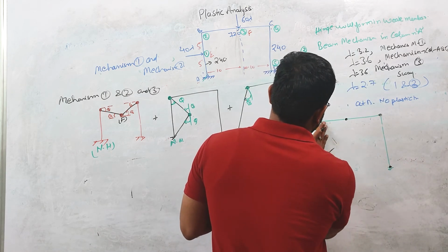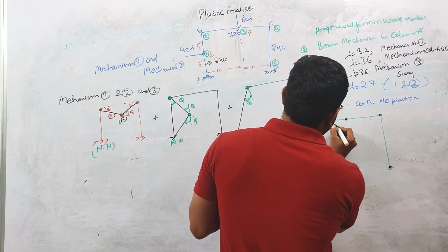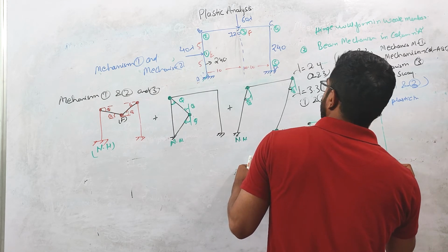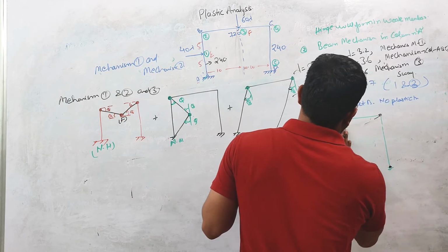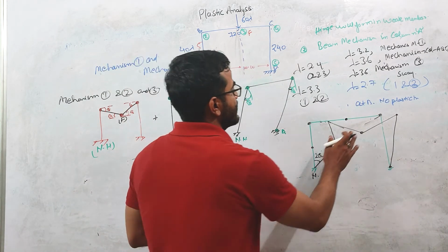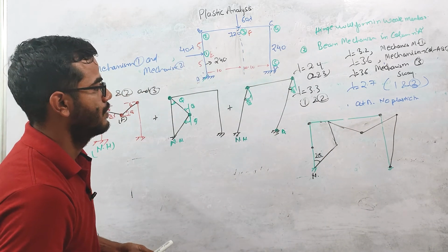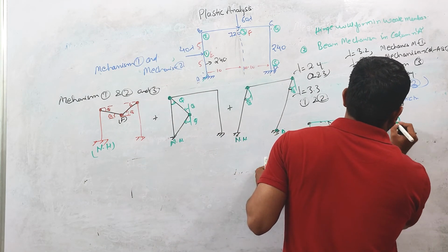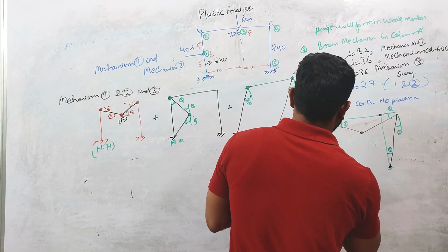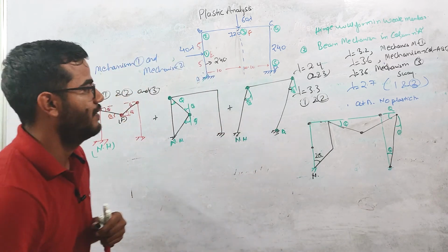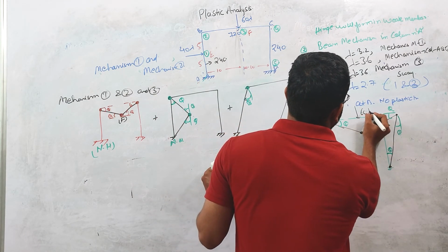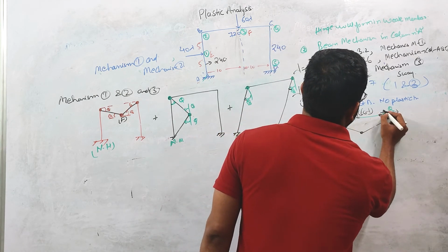This will go straight and this will bend like this. Okay, our deflection during the collapse will look like this. This is theta, this is theta, this is again theta. Okay, this is theta, right? So at this point the 40 lambda load is acting. Similarly at this point the 60 lambda load is acting. Okay, this distance will be equal to this distance, member inextensibility, right?